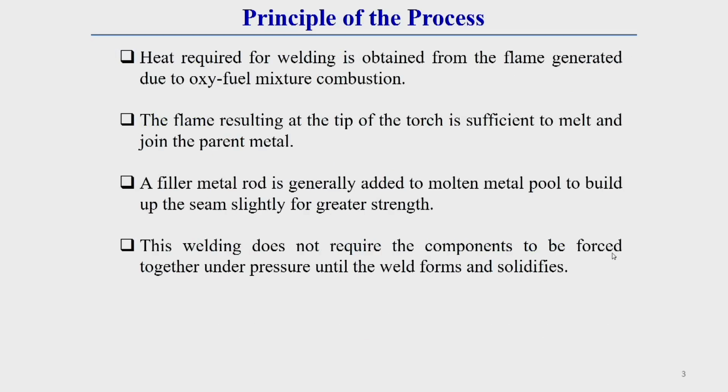First of all, we will discuss the principle of this welding technique. The principle lies in the definition of welding itself. The heat required for welding is obtained from the flame generated by the combustion of an oxy-fuel mixture, and the flame resulting at the tip of the torch is sufficient to melt and join the parent material.